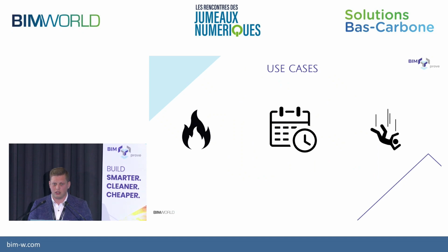The whole project focused on 3 basic use cases: fire protection, fall from height, and scheduling. Our construction schedule depends on multiple factors. It's not only that we plan that the supplier will arrive at exactly that second, because different situations occur on a construction site. For example, fire. I work in Norway, so on construction sites we have heaters for workers in winter, and if they are put too close to flammable materials, we may get a fire, not even directly at that moment, but 2, 3, 4, 5 hours after the day ends.